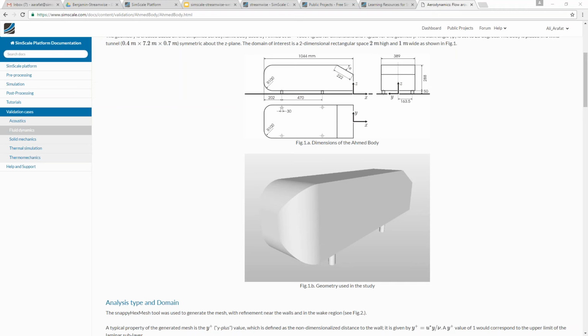One comment from my side to Krishna. Of course, classical C-grid topology for airfoils is a very good approach, and it also works together with OpenFOAM. It's just that the meshing approach is slightly different here. But if you have C-grid topology grids that you would like to upload, you can go ahead and do so, no problem. You can upload all of the meshes that you have from other tools, convert them to the OpenFOAM format and use them for simulations also. I hope that answers the question.